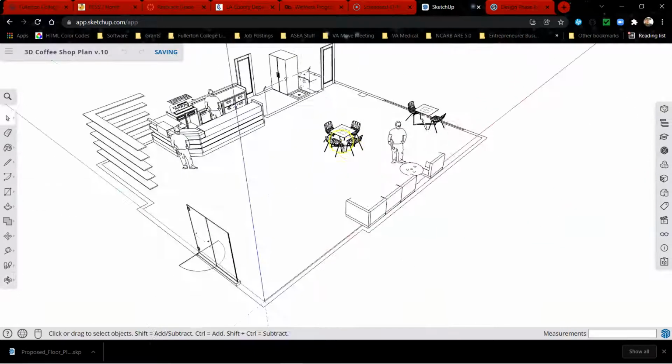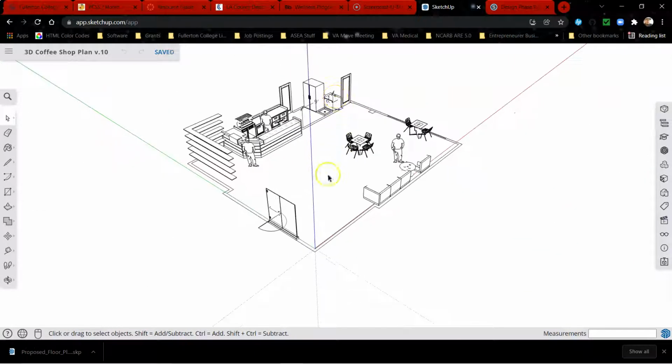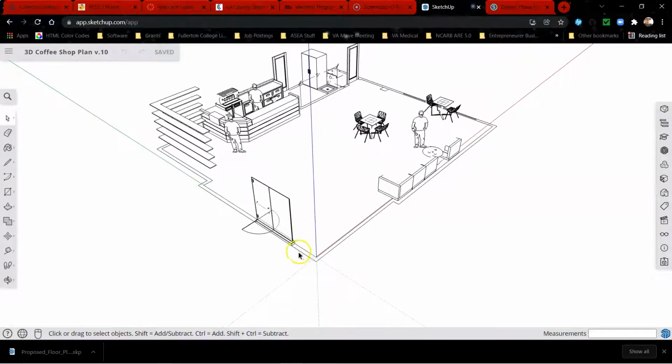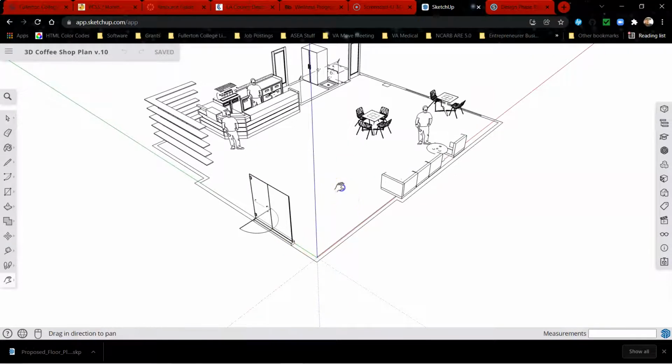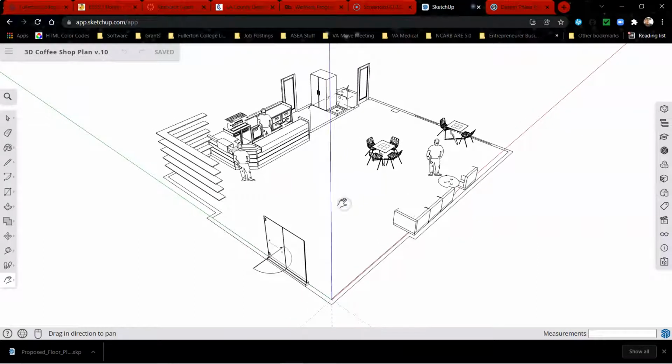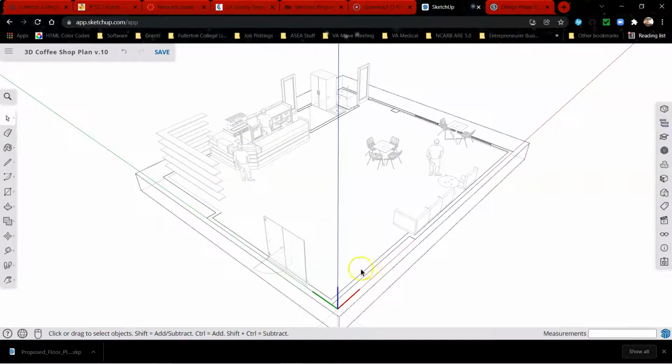It is in black and white. And so go ahead and position this like this. I'm going to show you how to pull up these walls. And so this is the hand command, the letter H, and I'm just positioning this. I'm going to go back into the select command, which is the space bar, and I'm going to double click on this floor plan. Remember, we had made this a component. We can't do anything to this while it's like this. We have to double click into it so we can manipulate it.